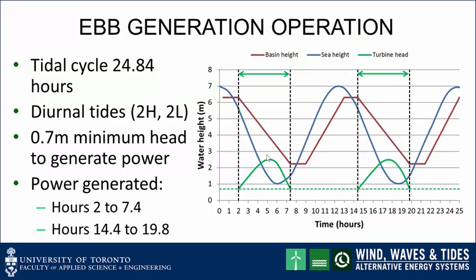It's not an optimized example, but just to give you an idea of how the process works. And what this shows us, of course, is that sizing the turbines, determining the flow characteristics, how fast this water level falls off, is a really important iterative exercise that has a big impact on the overall energy output of the barrage system.